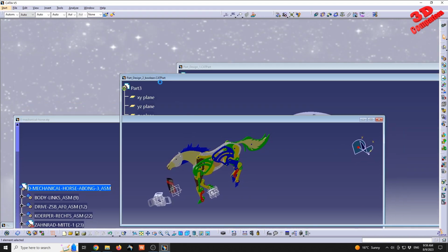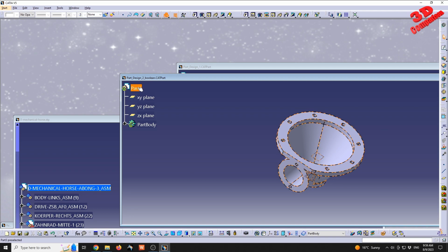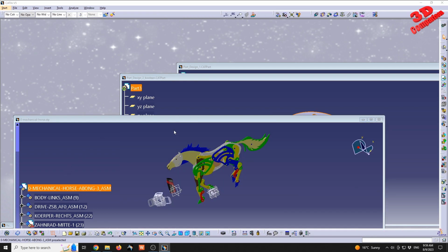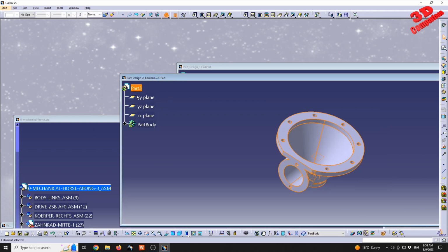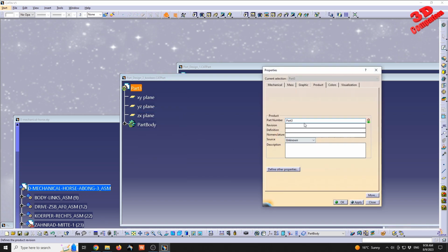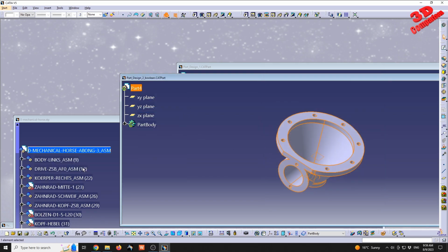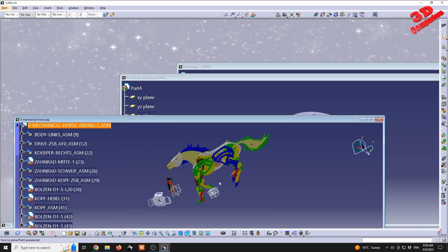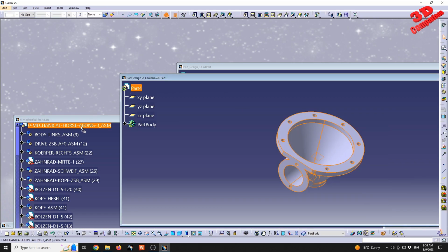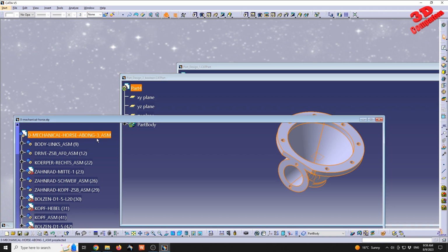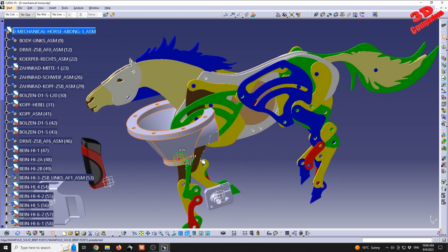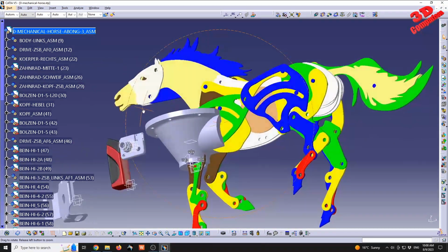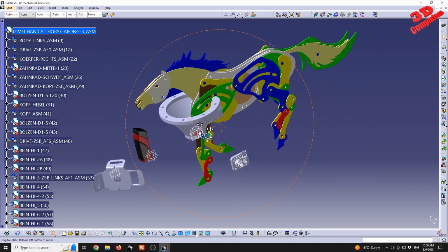So make this a little bit smaller, part 3, have that selected in orange, drag and drop on top of the mechanical horse. And we see that we had that naming. So let me see, part 4 then. Now drag and drop that part 4 over here, and we no longer have that naming problem. Okay, so since this part was created with Boolean operations, if I move it, some of the cutting will no longer be active, so I will leave it like this.